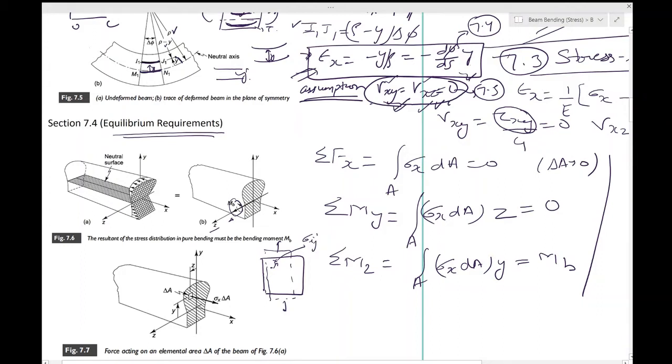Despite knowing that stress and strain only act when there has been some deformation, we still say that the stress at this point is what we have found out. Stress and strain at this original undeformed point. Even though the point has now moved here, we say that the stress and strain which we are finding using the theory of elasticity are at this undeformed point.